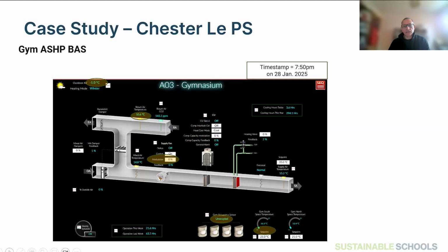Just a note, I was going to say that this, I think you mentioned, this is a very atypical system. Yeah. So this is a building that already had existing boilers that were actually replaced in 2019. So we had a new boiler plant with piping to all the existing air handlers that got replaced. So this is why you see hydronic heating coils, not gas fired, because that's what we had to work with. But hydronic heating, actually, from the point of view of controls, is actually better, because you will be able to fine tune the supply air temperature to whatever we want. So it's actually a bonus for us.